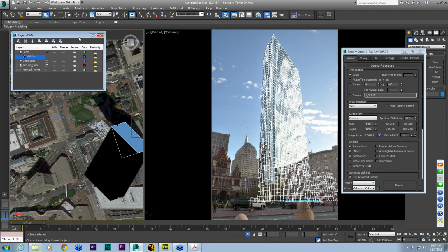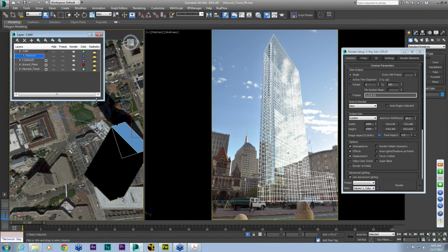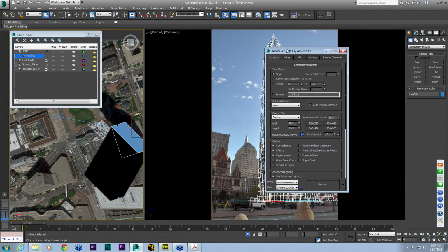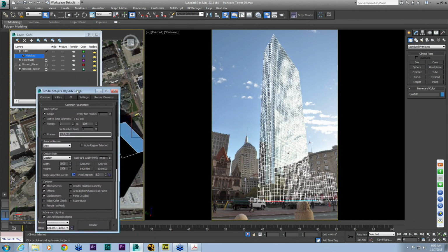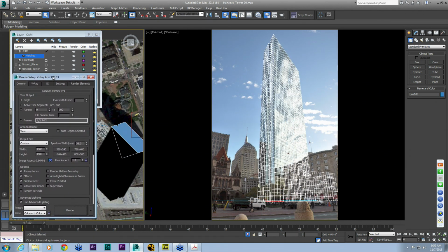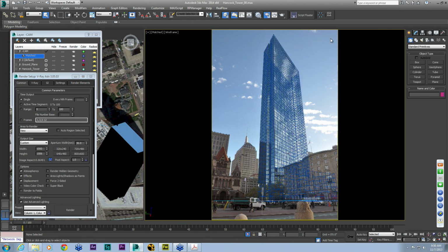But what becomes a challenge with this particular camera and this particular 3D environment is that, for one, I rotated the camera 90 degrees on the tripod, so it's not using the horizontal aspect ratio that V-Ray cameras are standard setup for. And like I said, it's a crop sensor, so you have to be mindful of that as well. Rotating the camera on the tripod 90 degrees means you have to convert the field of view.